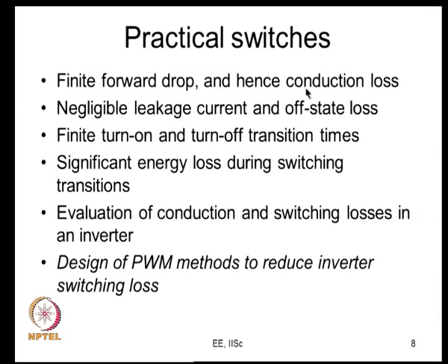So, we evaluate conduction loss and switching loss, etc., and today we are hoping to design PWM methods which would reduce the inverter switching loss significantly compared to something like sine triangle PWM or conventional space vector PWM. Alright, I would emphasize the fact that there is a reduction in switching loss, not really conduction loss, but it